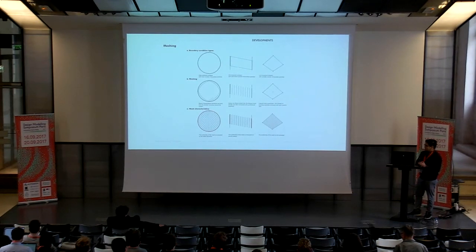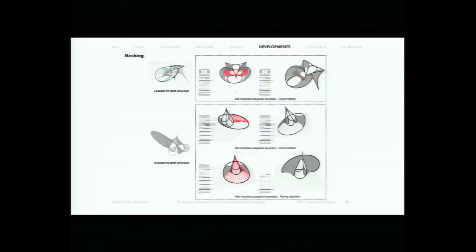The core idea behind this is the continuous creation of regular quad meshes, because we prefer the use of quad meshes here since the 2 local directions of the mesh can be directly associated with the weaving directions of the tensile fabric, and because quad faces can be easily converted into triangular ones. 3 types of algorithms were selected in order to conduct different kinds of meshing procedures within different recurrent boundary conditions.